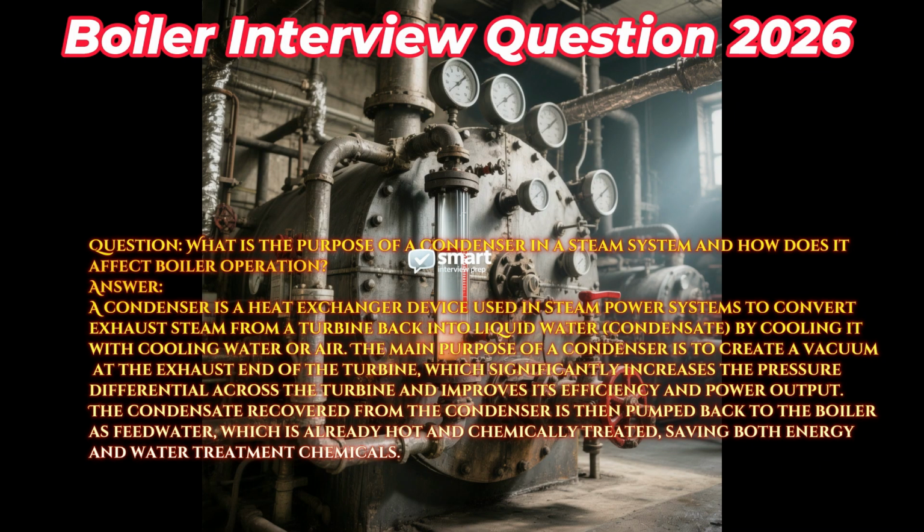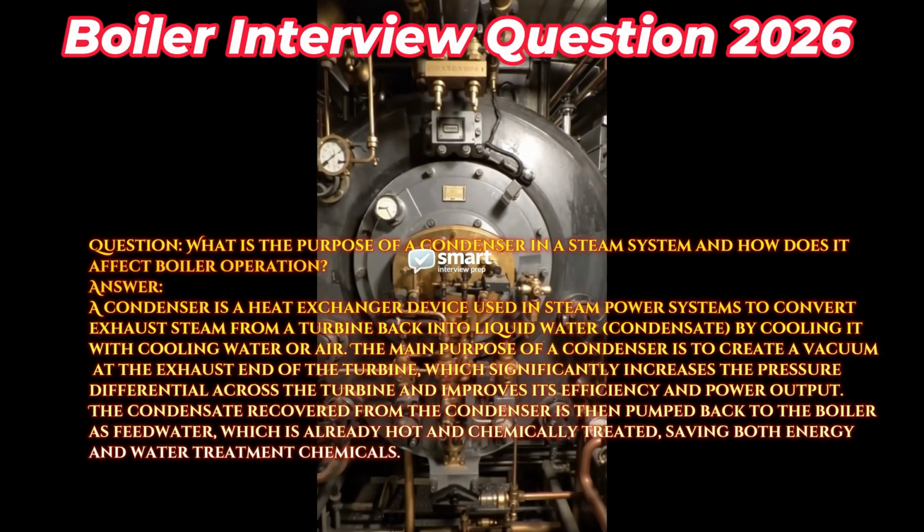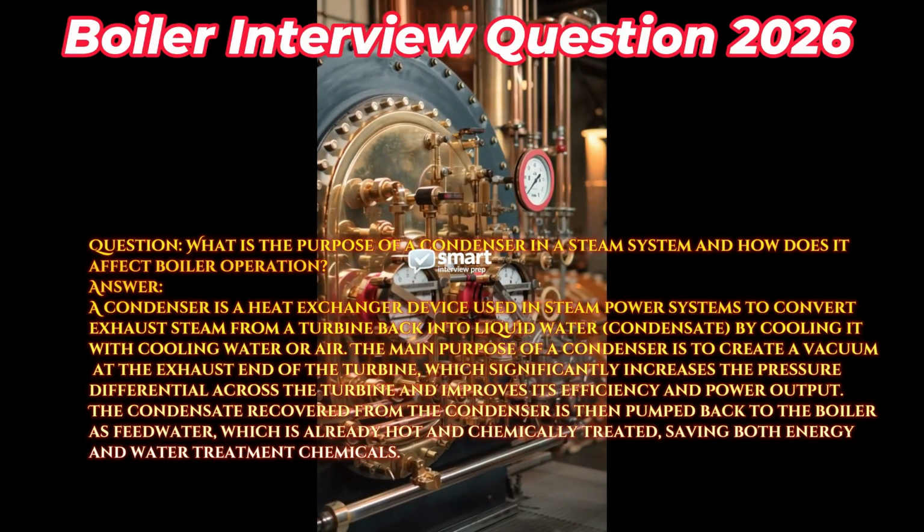The condensate recovered from the condenser is then pumped back to the boiler as feed water, which is already hot and chemically treated, saving both energy and water treatment chemicals.